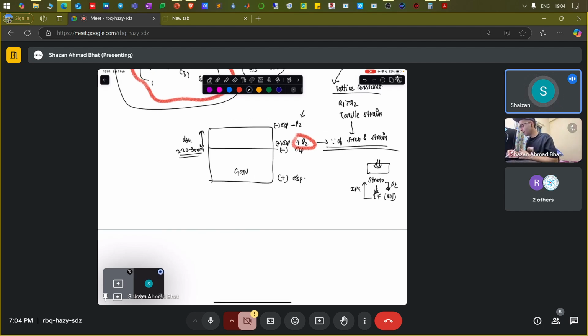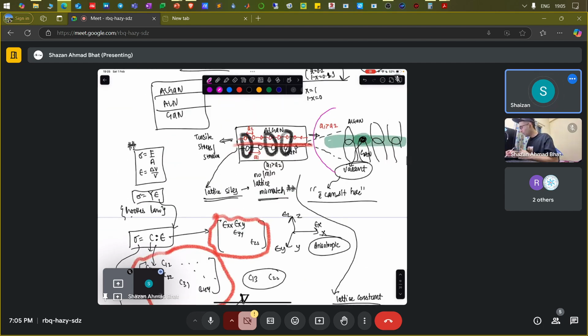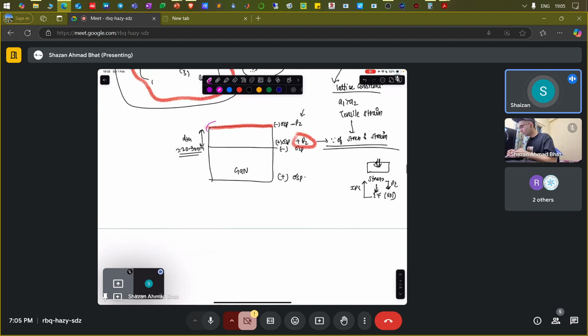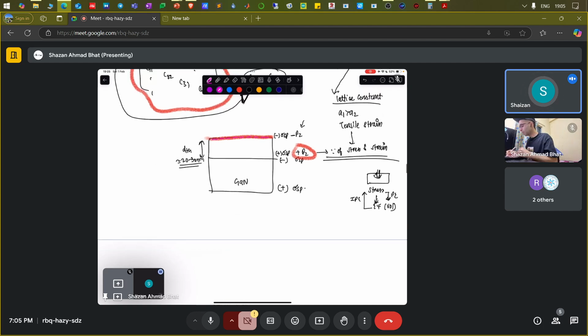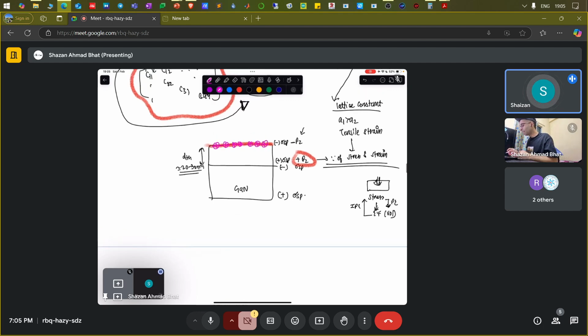If you have surface states here now. At this particular site, you have surface states of aluminum gallium nitride because you have not terminated it with any of the materials on the top. Just like you terminated the bonds in gallium nitride with aluminum gallium nitride in this figure, if you don't terminate these sites, then there will be surface states. And those surface states, mostly donor type, are positively charged and they give away the electrons. Okay, why do they give away the electron?